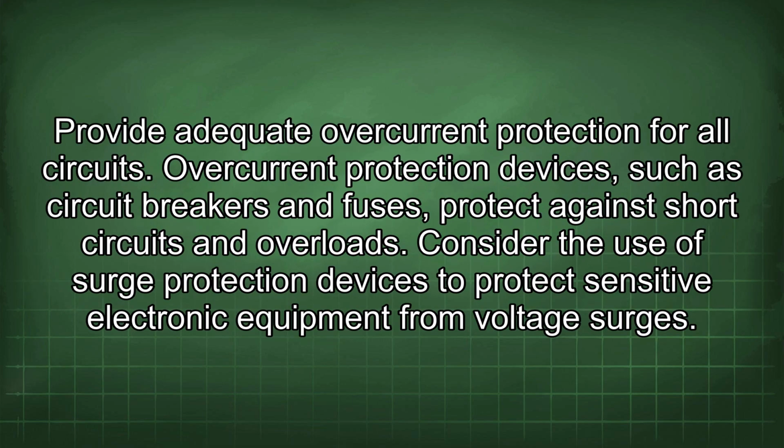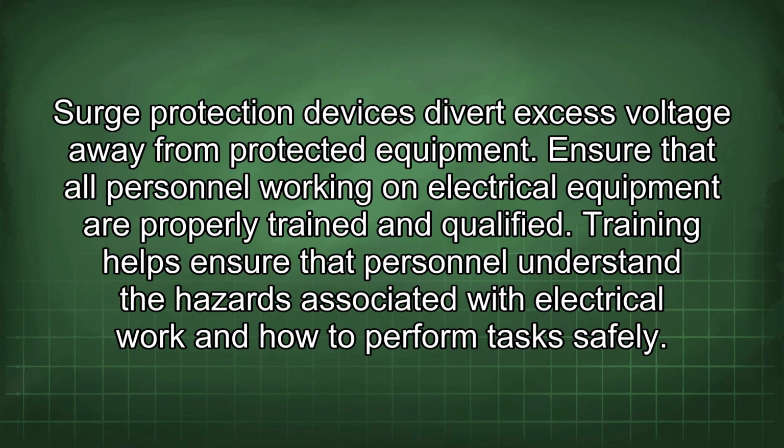Provide adequate overcurrent protection for all circuits. Overcurrent protection devices, such as circuit breakers and fuses, protect against short circuits and overloads. Consider the use of surge protection devices to protect sensitive electronic equipment from voltage surges. Surge protection devices divert excess voltage away from protected equipment.